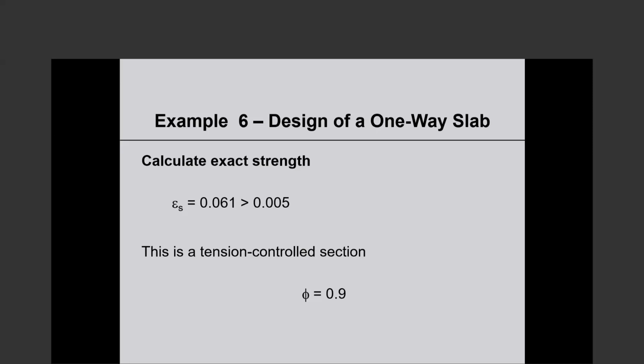If required compression steel in a beam is found high, and if a, that small a, is less than the slab thickness, can we distribute rebars in part of the adjacent slab to avoid congestion?